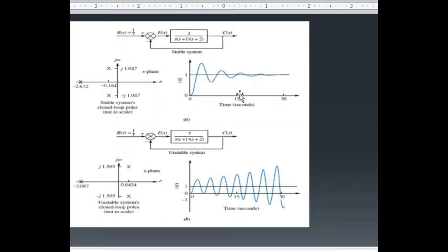In such a case, when you plot it, for example for a second order system, you will see that the system has one response, then it settles down to the final value of 1, as plotted here. So your system is stable. Now consider another case, down here. Once you solve for it, you find the closed loop transfer function, and you look for the poles of the system by looking at the polynomial of the denominator.